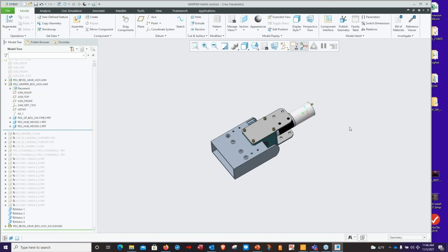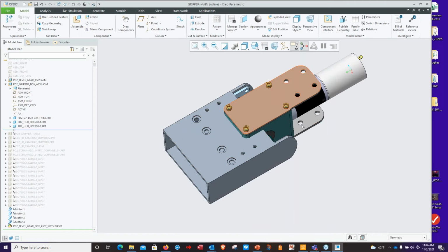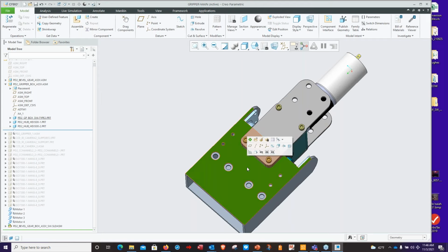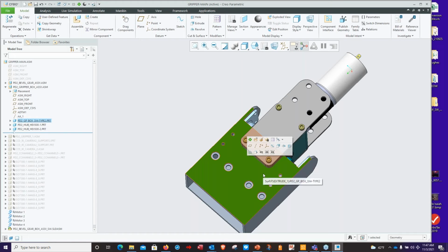Okay. So we've assembled this SolidWorks file on here, and as we see, this component we've been waiting for impacts this Creo part file that we're responsible for. So in Creo, it's easy. We want to integrate or modify this part to reflect this model so we can receive that and complete the assembly. Again, Creo is intuitive. We can select a surface on a part that we need to modify. It'll highlight it in the model tree.